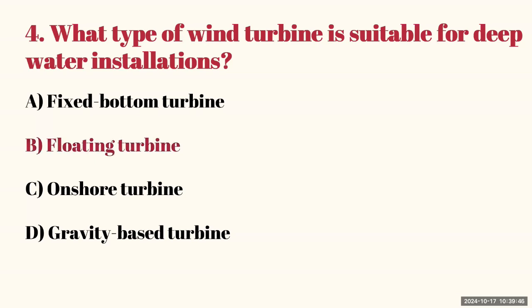Okay, so the answer for this question is B, floating turbine. So a fixed bottom turbine can be used for sea, but not very deep. So usually, if it's deeper than 60 meters below sea level, a floating turbine would be the suitable technology.